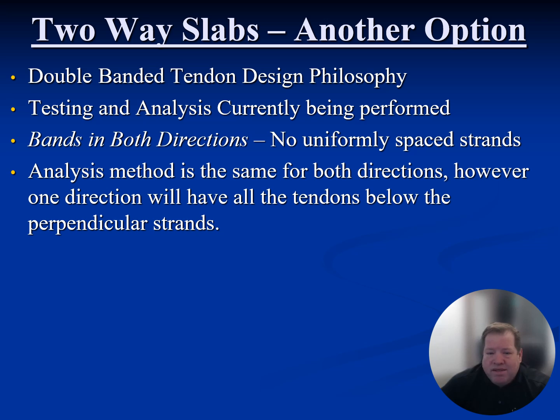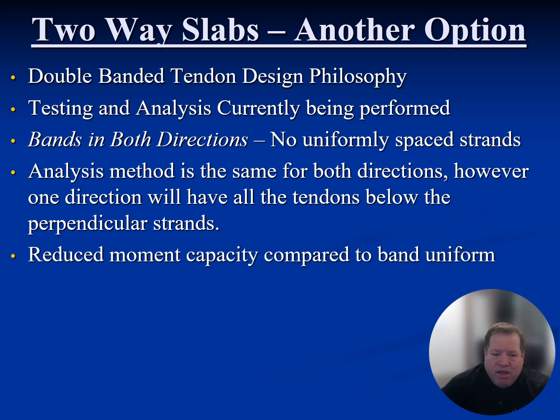Again, the analysis is exactly the same. The only difference is in one direction, the tendons will all be a ½ inch lower. So technically speaking, there's a slight reduction in moment capacity. But again, you're talking about some percentage points, not factors of 2.